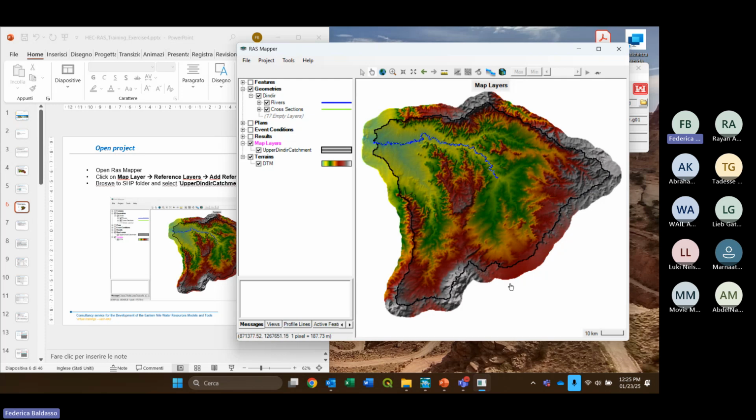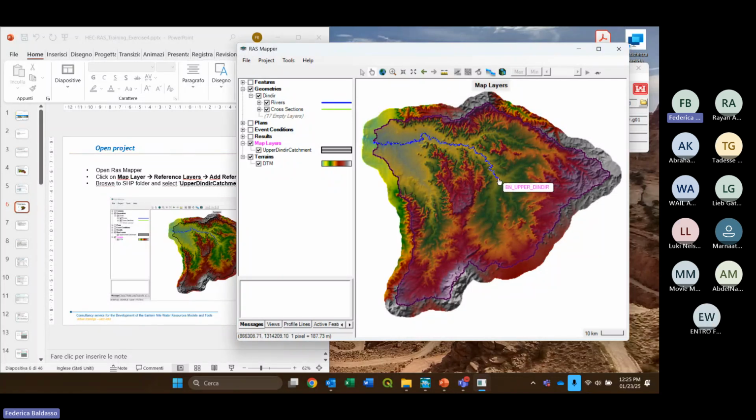We want to use that flow hydrograph as an input for our hydraulic simulation, just splitting the total flow hydrograph in the way I just described. One part will be used as a boundary condition, as a flow which is directly emitted in our system from the upstream cross-section, while the remaining parts of the flow hydrograph will be distributed along the river.